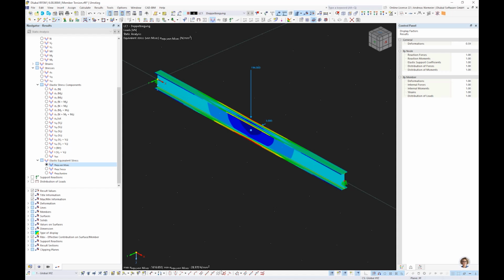But you always have to grasp reality. Is the program able to consider this effect here? We have an open cross section with a biaxial bending, which should induce some torsion. And the challenge is that the program knows only 6 degrees of freedom. It has no warping stiffness in it, and without considering this warping stiffness, you are not really able to model such things with members.